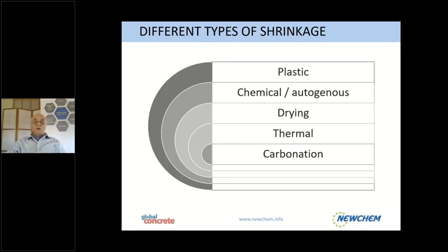Once you pour your concrete and the surface is getting dry, you get micro cracks normally. If you can cure it or keep it wet on the surface, then these micro cracks will not appear. If they do appear, it's a weak point where later on with shrinkage, the cracks will develop into bigger cracks.